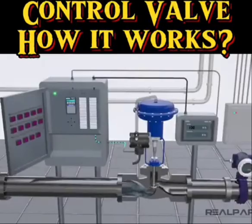that provides a signal from a controller, such as a PLC or a DCS, in order to operate. The controller compares the actual flow rate to the desired flow value, called the set point. The controller will produce an output to move the valve to bring the flow rate to the set point value.